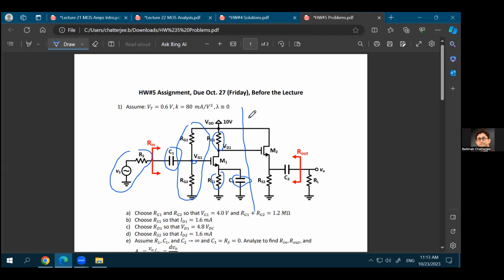What you don't know yet is the behavior of this part of the circuit, specifically this MOSFET and this resistance configuration. But what you see here is that the input is provided at the gate, right? The output is taken from the source of the MOSFET. Remember that this is the source terminal; the current direction is always provided on the source terminal. And the drain terminal is connected to the AC ground, which is your VDD. So in this case, your input is at the gate, output is at the source, whereas the drain terminal is the common or reference terminal. So this is called a common drain configuration.